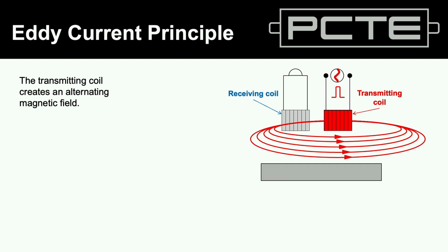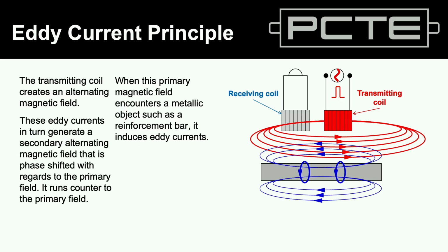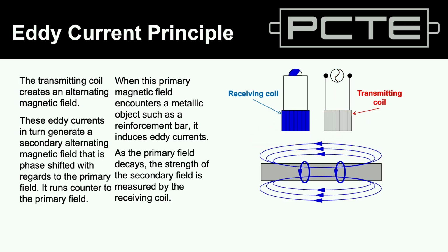They will receive a pulsed eddy current actuation, so they'll turn on and produce an electromagnetic field. So the current flowing through the steel will produce its own electromagnetic field, and once that's been produced, we're then going to turn off the transmitting coil and measure the signal intensity on the receiving coil. And it's the intensity of that return signal that we convert to depth.